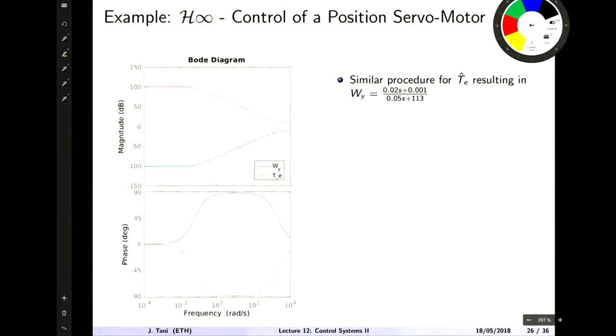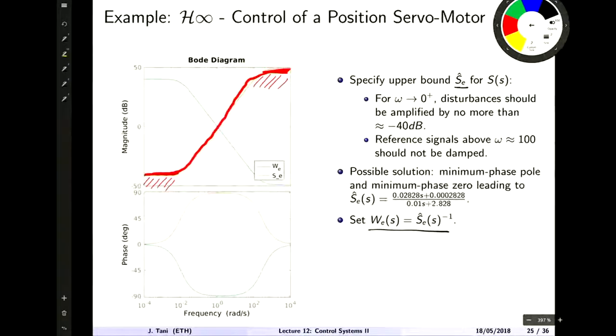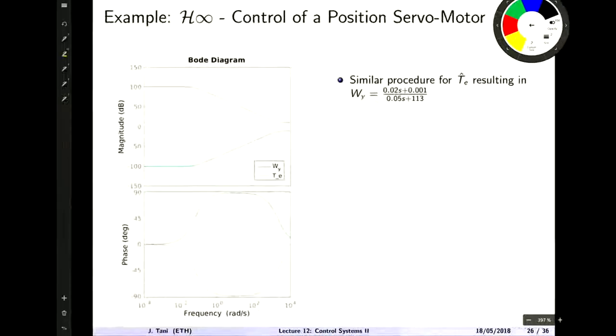We do the very same for T. I didn't place so much emphasis on this one. That's what gave me a good result. I focused mostly on the sensitivity on the bounds. Oh yeah, by the way, what we see here is omega c, so the crossover frequency, and T has an upper bound which is still high enough here, right?